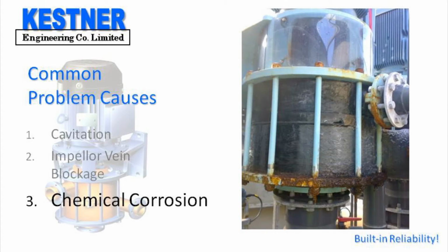It can be clearly seen here, the upper rotor casing as a whole corroded right through. This was due to sodium hypochlorite at a very high concentration, which was not disclosed to us before the manufacture of this pump.